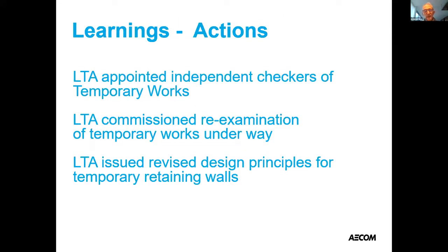So what was learned from this? The client appointed independent checkers for temporary works. They commissioned re-examination of all temporary works that were underway and revised design principles for temporary retaining walls.